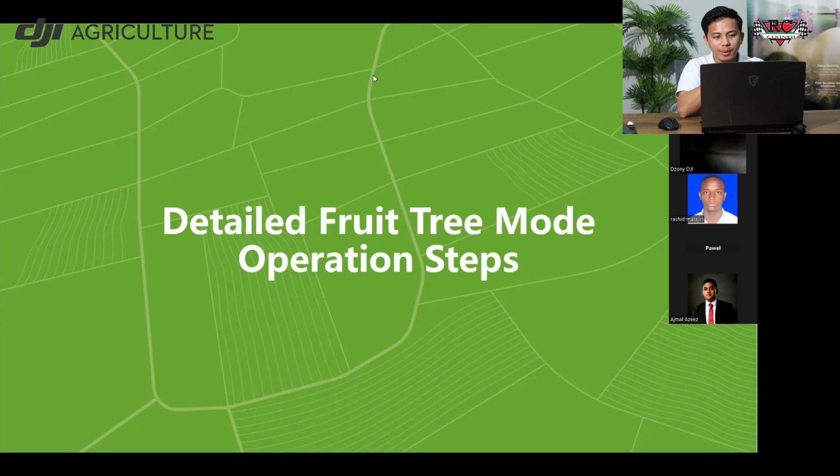But I suggest using RTK for higher accuracy, especially if you go for spot spray, one by one trees, it is a must. Either an RTK base station, or you can use RTK network. I can say it's a must because we use fruit tree mapping for accuracy purposes. RTK is real-time kinematic, so it helps us for this reason.